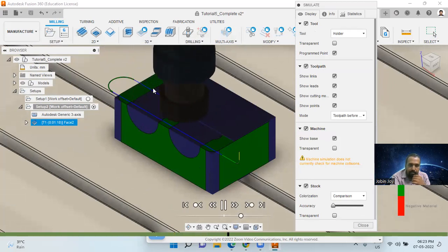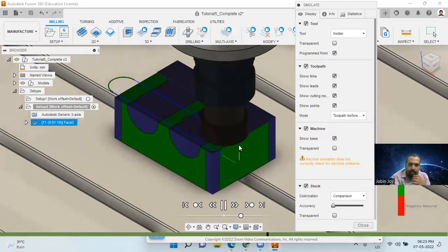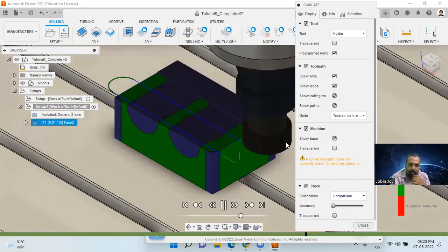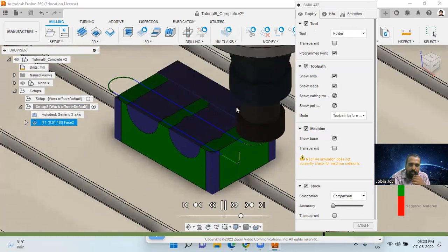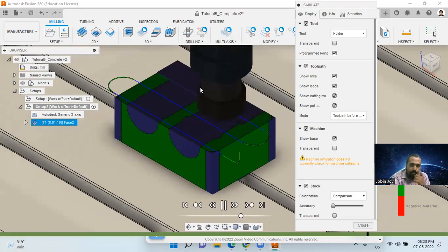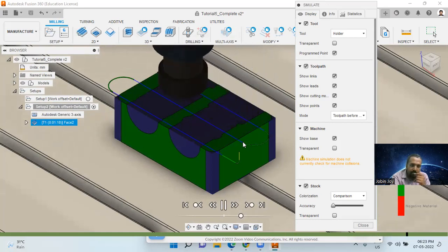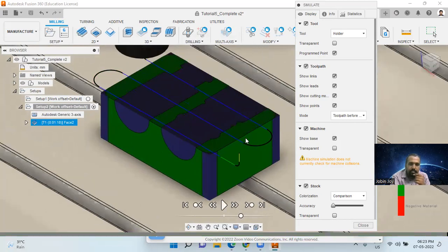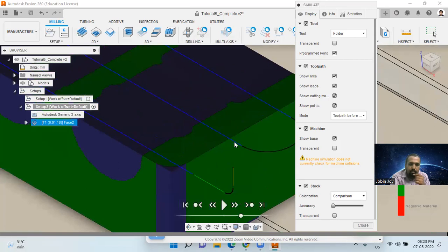Here this is the second blue line, and then from here there will be a circular and the third blue line, that is the third cutting. And this distance is the pass extension, the distance from the machining boundary. The pass extension is given as 8 millimeter.